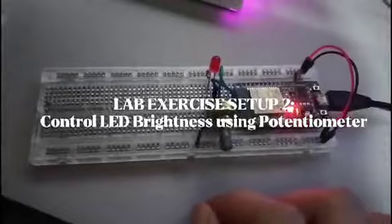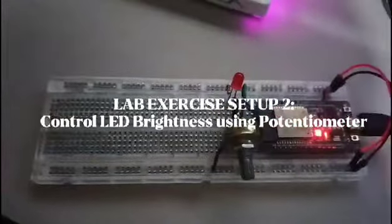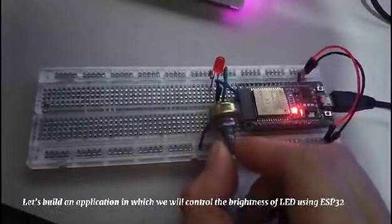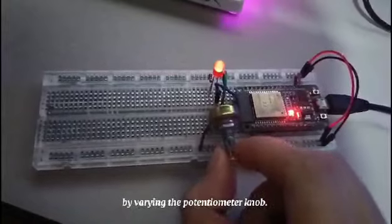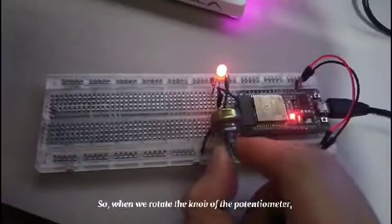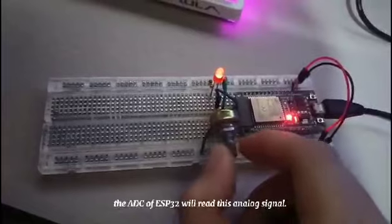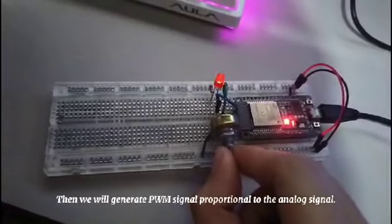Lab exercise setup 2. Control LED brightness using potentiometer. Let's build an application in which we will control the brightness of an LED using the ESP32 by varying the potentiometer knob. So, when we rotate the knob of the potentiometer, the ADC of the ESP32 will read this analog signal. Then we will generate a PWM signal proportional to the analog signal.